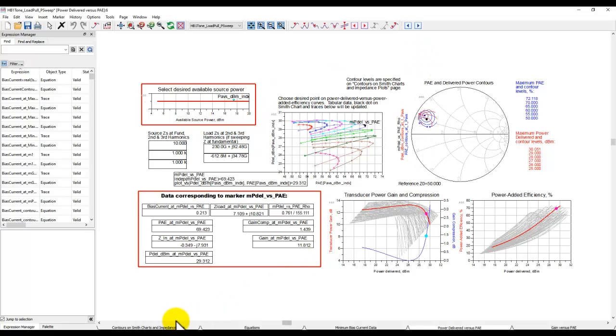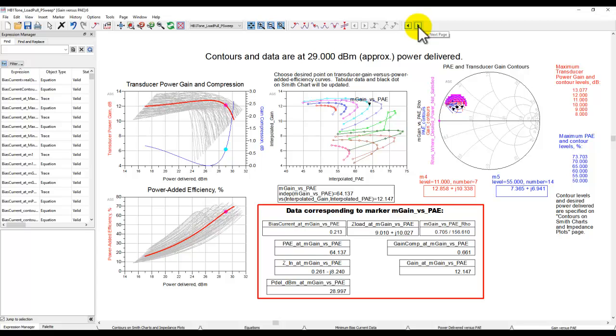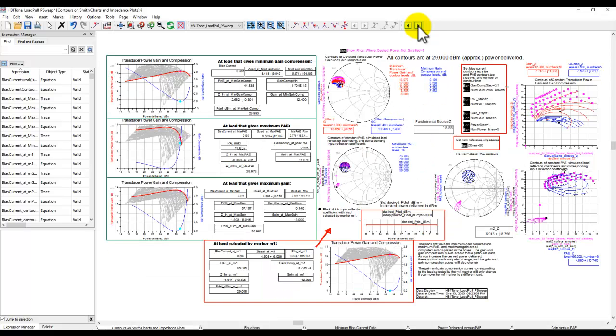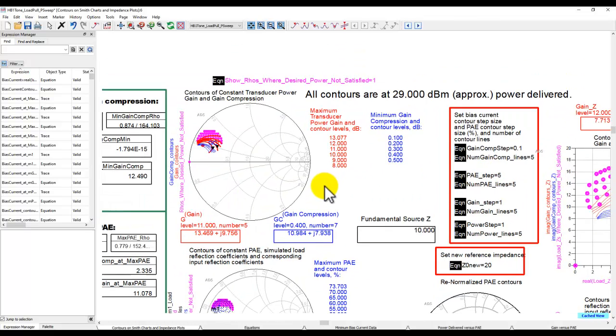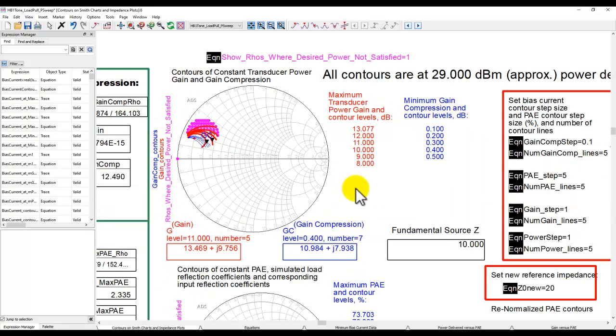Now again, this data display, if you look at the bottom, it has various tabs. If you have switched on this page change toolbar here, and you can do that very simply by right clicking and switching on the page, this allows you to flip into different pages. So here is another way of looking at the same data. Then you push forward, and again, you will have the regular data display, but here you can see you have the power swept data like what I showed you earlier in my simple schematic. And here the interesting thing, you can see the amount of data mining possible.